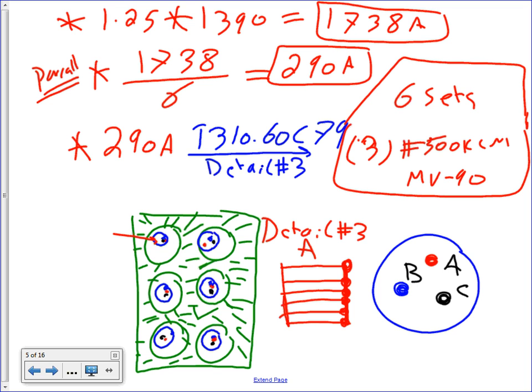It's going to look like concrete encased ducts like this, PVC or concrete ducts that they make. You put three phases in one duct. They look like this: phase A, phase B, phase C, A, B, C. And when they parallel them, here's phase A, here's conductor 1, 2, 3, 4, 5, 6 conductors for phase A. So phase A will have 6 conductors tied from both ends.